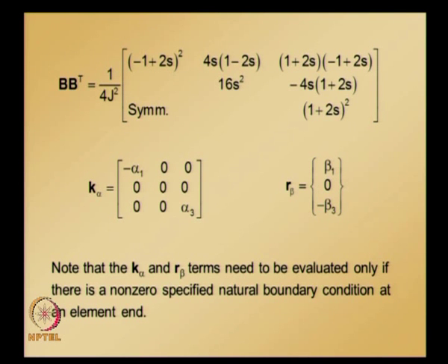If you recall, when we discretized the domain using 4 linear elements, we noticed that the critical buckling load that we obtained for the column buckling problem has about 5% error. Now let us see how much improvement we get using this quadratic element for the same number of nodes for the entire domain.